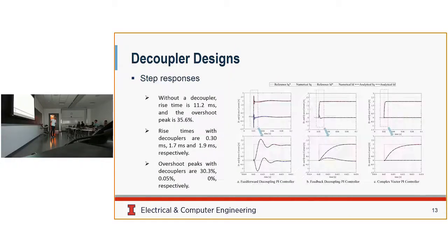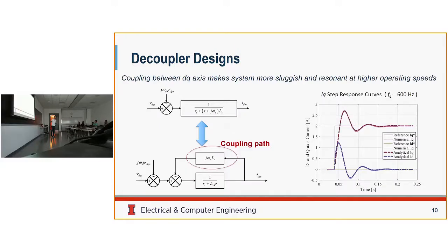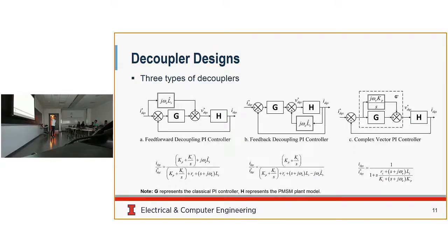If you look at the coupling terms and the decoupling terms, it's a reactance factor coefficient, but your PI controller tuning is based on your ratio of Rs and Ls. So it determines your global gain in the system. So that really needs to be accounted for in operation, like online estimation of the resistance.